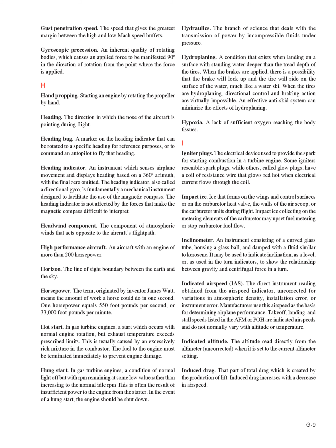Hot start. In gas turbine engines, a start which occurs with normal engine rotation, but exhaust temperature exceeds prescribed limits. This is usually caused by an excessively rich mixture in the combustor. The fuel to the engine must be terminated immediately to prevent engine damage.